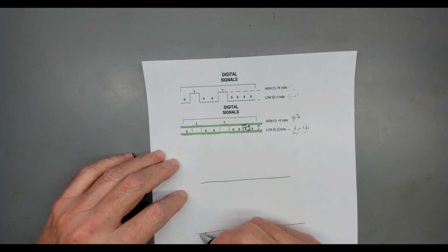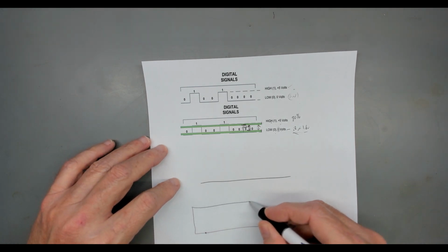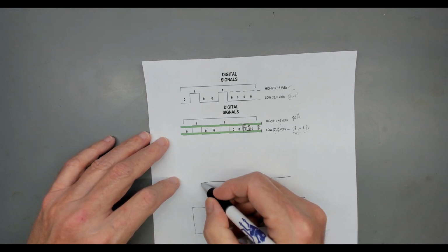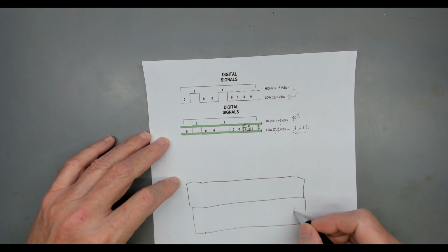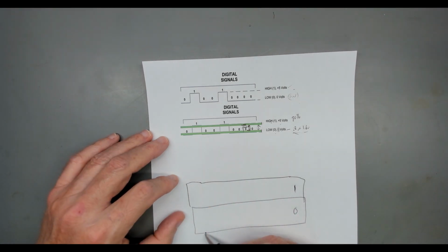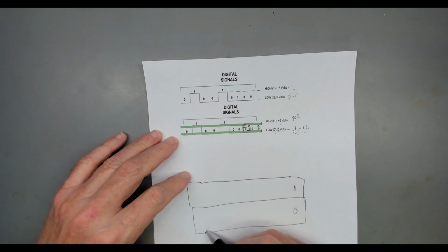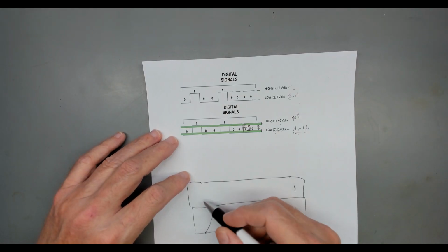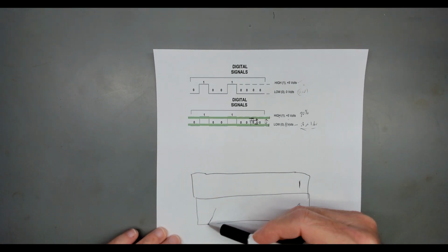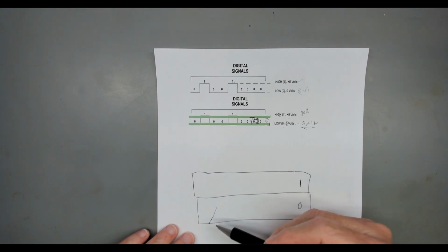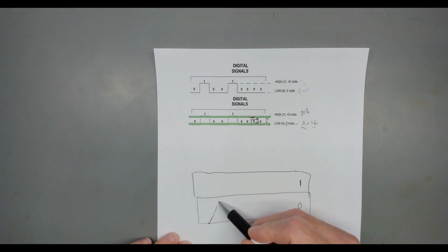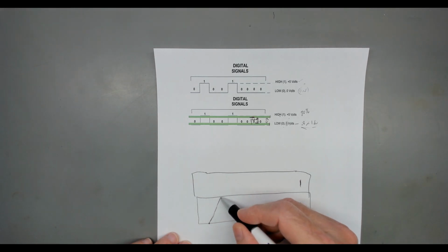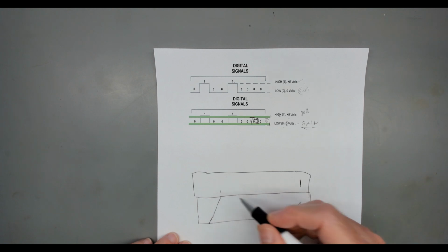So let's say that it's the way that most people that don't work with digital electronics believe it works. We're going to do 2 bars here. We're going to call this 0 and it's 1 here. You're 0 and the voltage, you say, okay, I'm switching to 1. You turn the power on and it starts rising. Well, it doesn't instantly go up. As you know, there's always a little inductance and capacitance and everything. It doesn't go straight up. It slopes upwards. At some point, it will break this threshold and switch to become a 1 right here.